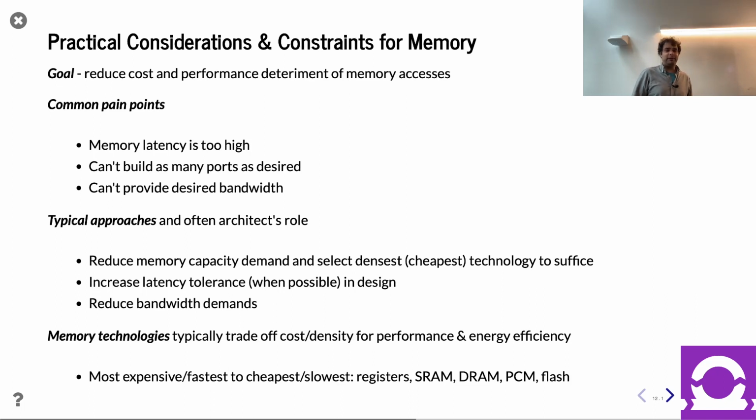For example, for a register file on a big superscalar out-of-order processor, if you want to go 8 or 12 wide, let's say you want to go 8 wide and you expect each lane in your CPU requires 1.5 operands on average, you're going to need 12 ports, right? So architecturally, you're going to have that need, but physically, it's not always possible. So we're talking today about how to solve that. Architecturally, what can you do? Given your physical constraints, how can you change your design to handle that?